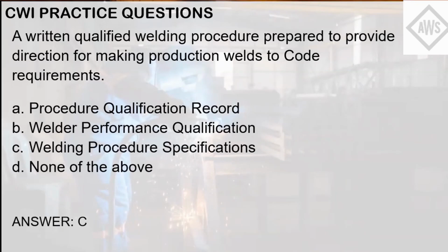This welding document is like a recipe or a written step-by-step procedure that is used by the welder in making sound production welds. So this is the document that the welding inspector should refer to as well in ensuring that the quality assurance documents are being followed at site, because this has been proven to produce sound welds.